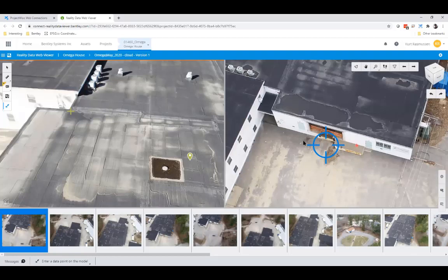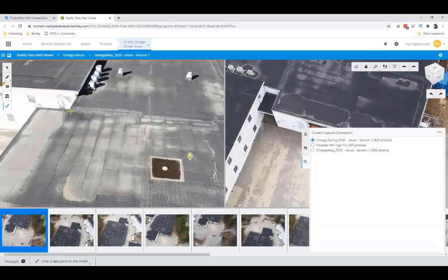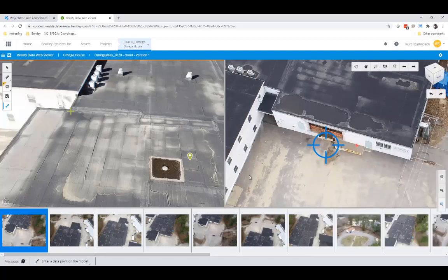So that goes to show two different flights that I did with the same drone, probably during the same month, but definitely different days, gave me different locations. So this is why ground control is important. It's also important to know which flights I'm using. You know, these were just within a week of each other that I flew them. But depending on what satellites I'm hitting and things like that. So that shows how to do this here.